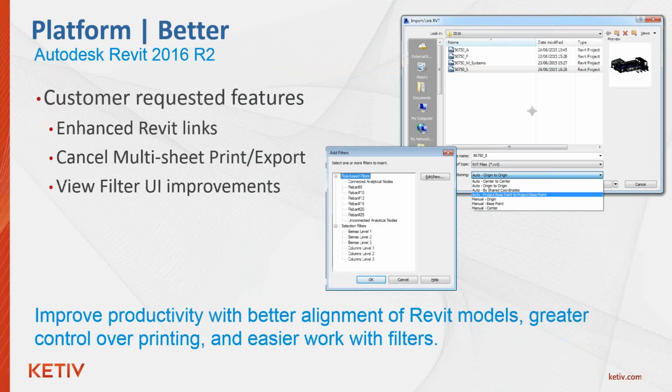All right, so let's jump into the customer requested features that are included in the Revit 2016 R2 update. So we have enhanced Revit links, which is a new positioning option called Auto Project Base Point to Project Base Point, which is now available when inserting Revit links. This option positions the linked file using the model's project base point as the insertion point, and it aligns it to the project base point in the host model. This is a valuable alternative for Revit projects where you don't want to utilize the shared coordinates option, which could be a pain to use sometimes.